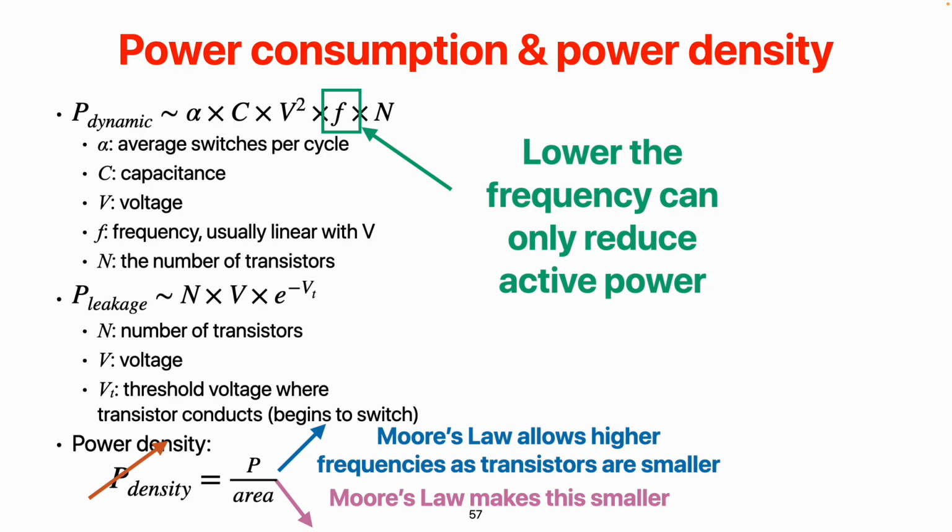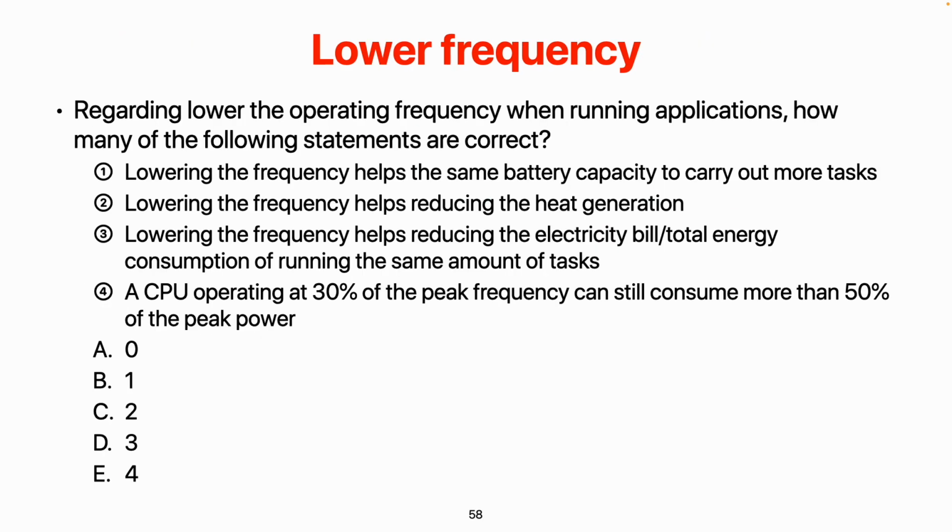That explains why, when you increase the density or use a newer, more advanced process technology, the power consumption doesn't go down. Because the more transistors you have, the more leakage power you have, and active power is only a small fraction of your power consumption.